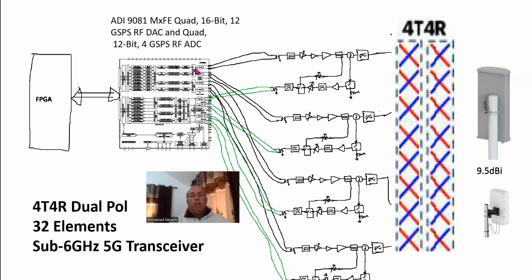What we did is we took each one of the DACs, with a balun and filtering, amplification, and then we went through a circulator, a two-way device, and then a harmonic filter on the transmit side to go out to the antennas. Likewise, the receive path is driven from the same circulator down to this switch that opens the receiver when transmitting, to protect the LNA. We have an LNA, and then we're going into an ADC. And you repeat this 4 times: 1, 2, 3, 4. So that's 4 transceivers, 4 receivers, 4 transmitters.